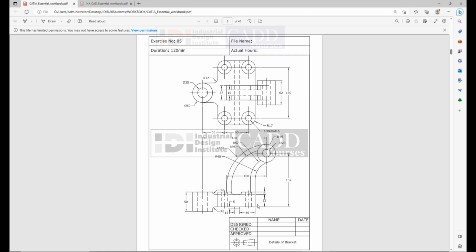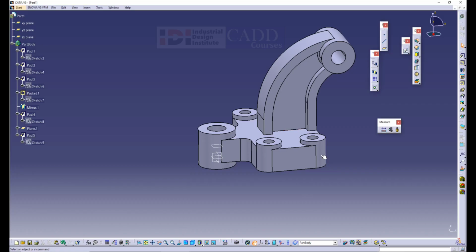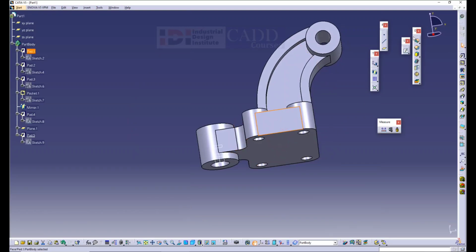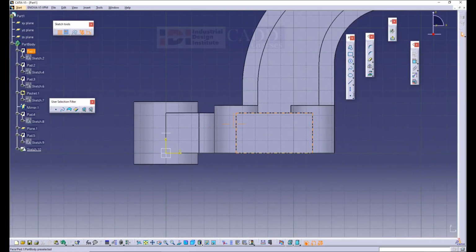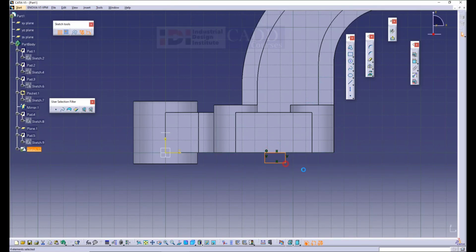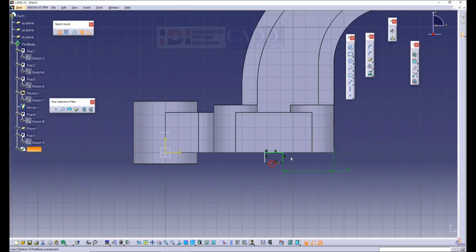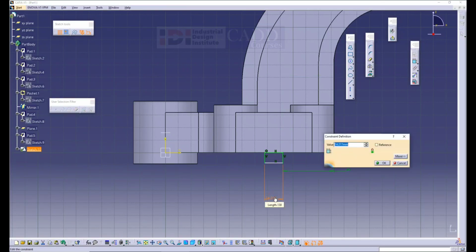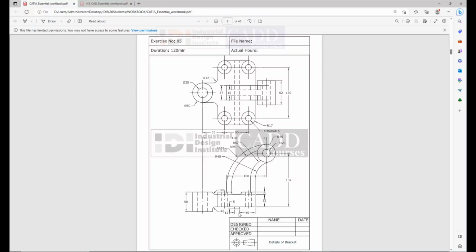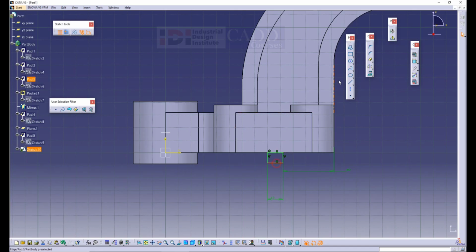Nice. So you can see some corner edges. There are some fillets, and I have to create a slot at the bottom. There are some parameters provided. Okay. So I take a plane edge. Now I create a rectangle block with respect to the edge. 40 mm distance, and this is almost 12 mm. Now what is the height? Height is almost, it's showing 8. I needed 5.